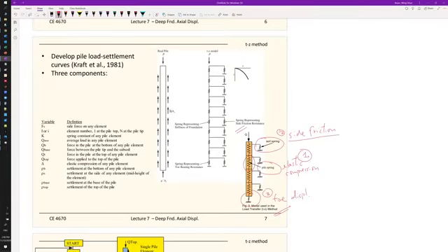So he has three sets of springs, and the side friction and the pile springs are a series of them, because another philosophy he has is to break down the long pile into different segments, a little bit like a finite element approach. He solved the problem element by element, chopping the information into pieces, and then you can pass on the distributions of the loading and also the displacements.